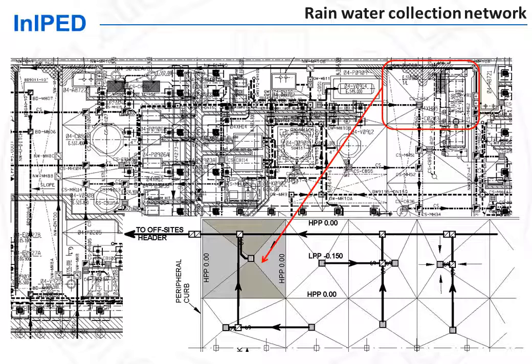The rainwater collection system, for instance, is a rather intricate collection of catch basins, and pits at every change of direction to be able to clean in case of blockage. In fact, there is not only one such system, but two systems in a process plant. One for clean water, collecting the rainwater on building roofs and roads, and one for oily water, collecting water on the paving of process areas. So you see that this system of rainwater collection is rather complicated.